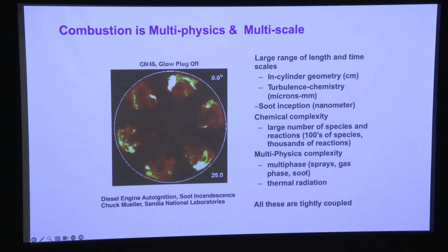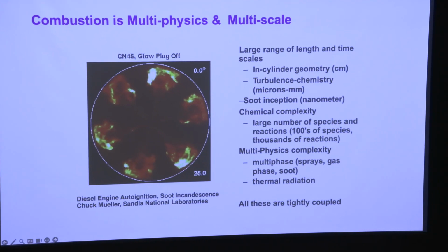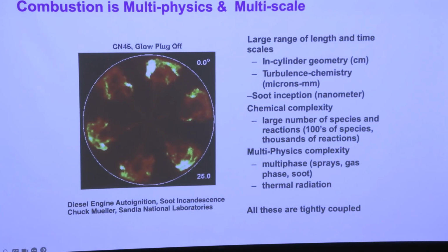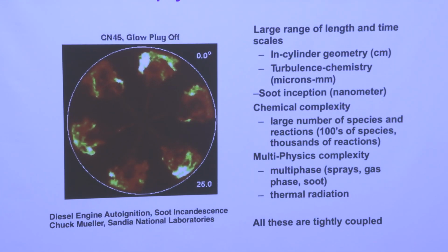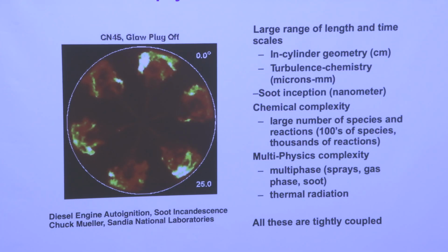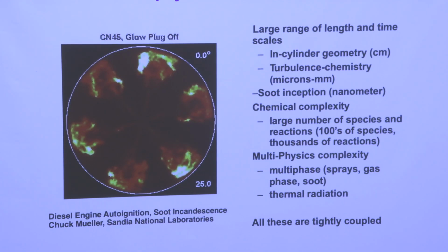And so looking at the combined interaction of turbulence, turbulent strain, turbulent mixing of the reactants, the fuels, and then the reactions occurring themselves can go from microns on up to meters. Similarly, soot inception and particulate formation starts at nanometer scales. So there's a very, very broad range of length and time scales involved in combustion.